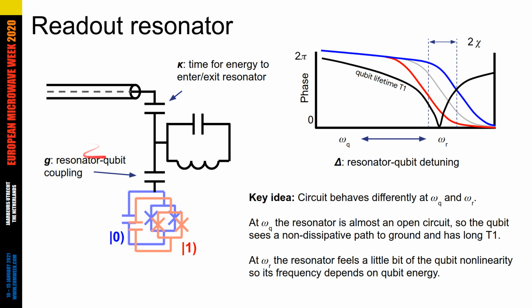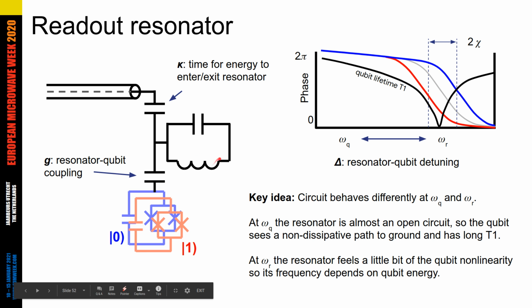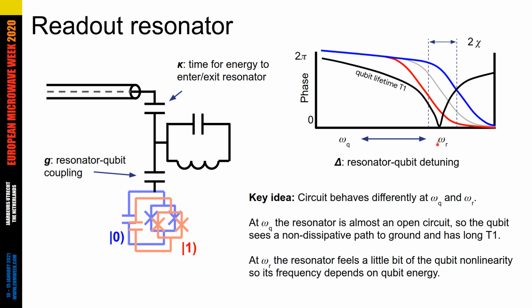So what we do to fix this is we add another resonance to the circuit. So here we've added a linear resonator in between the input-output line and the qubit itself. And it works like this. The resonator is at a frequency omega r, as shown here, and the qubit is detuned by a large amount here at omega q. Usually this detuning is a gigahertz or 1.5 gigahertz.